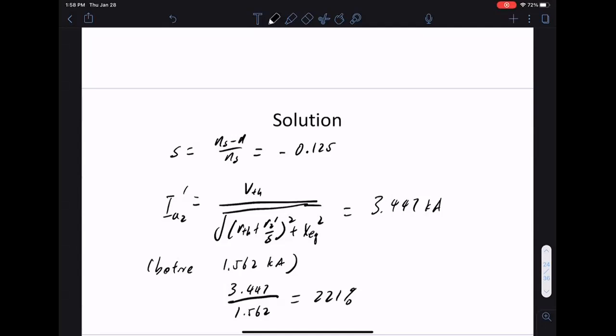That produces large current. In the system we have, the voltages are set pretty locally, right? A generator can maintain its voltage, and you have capacitors maintaining voltage. So you have a voltage that's fairly set. Even if a fault occurs, the voltage at the other parts of the grid doesn't change that much. However, if you have a short circuit fault, then you're basically connecting, let's say, power to ground, connecting the positive and negative together. That causes large current, and that's the thing you want to prevent, because this causes damage.